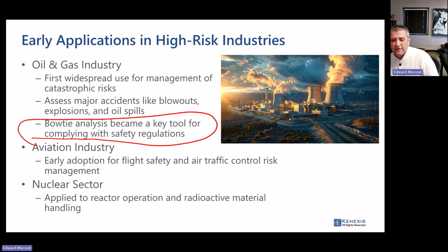Now, a lot of you in Australia, a lot of you in Europe, your regulators are demanding that you present to them bowtie diagrams of the major accident scenarios, and they use those bowtie diagrams as a map for how they're going to inspect your plant, looking at all the barriers, making sure that all the barriers are in service and have their associated testing records.